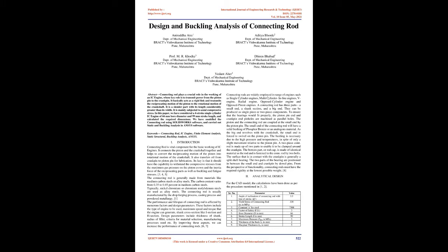In this paper, we have considered a 4-stroke single-cylinder IC engine of 66 mm bore diameter and 99 mm stroke length, and calculated the required dimensions. We have modeled the connecting rod using SOLIDWORKS software, and carried out static and buckling analysis in ANSYS software. Keywords: connecting rod, IC engine, finite element analysis, static structural, buckling analysis, ANSYS.